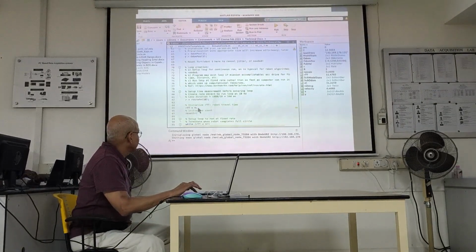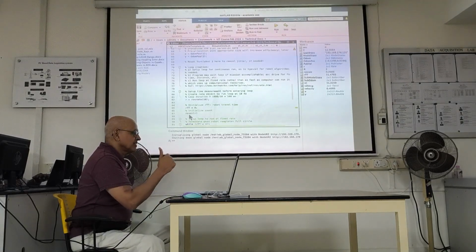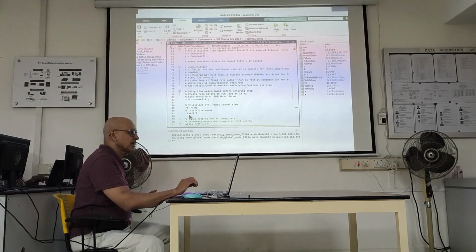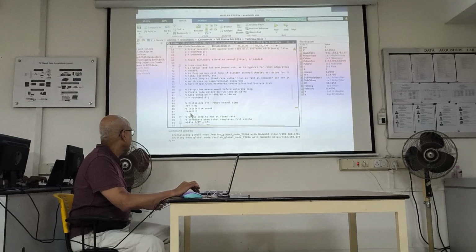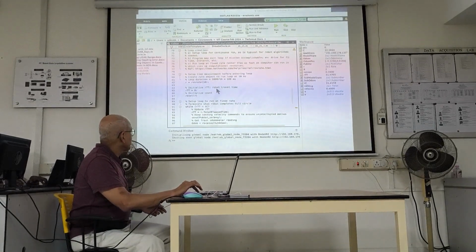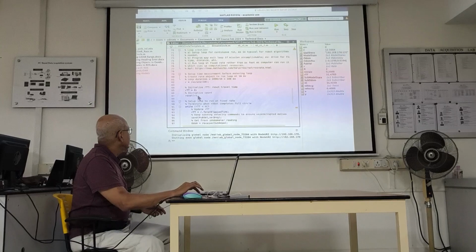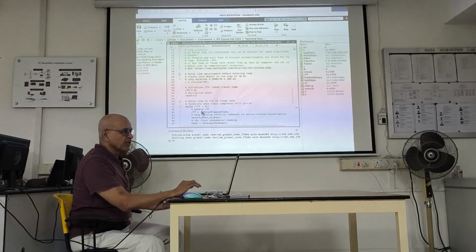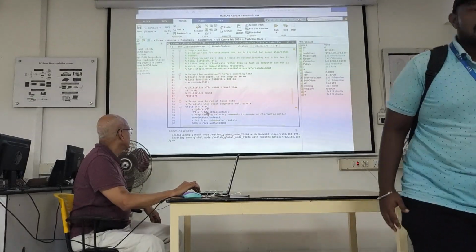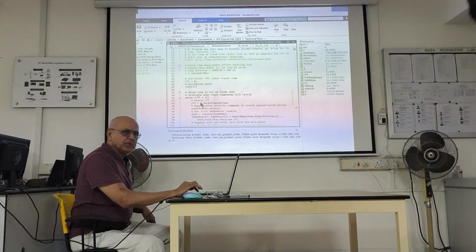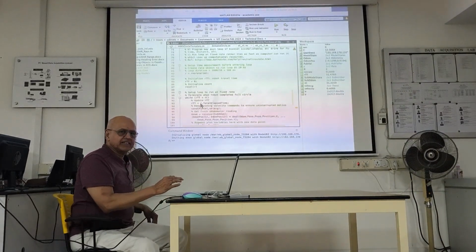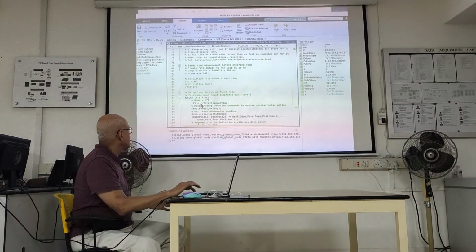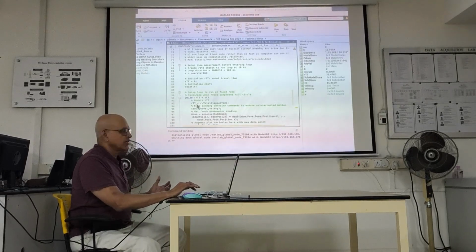So I initialize the robot travel time. I reset the clock, because I have to, right? Because when you're timing something, you have to start with a reset. It's like timing a runner in a race. And then I'm checking whether the robot travel time has exceeded the time to go around the circle. Now initially, obviously, it won't have because you initialized it at 0. And then the first thing you do in the loop is you update it. If you don't update this, it'll run forever. Got it? Obviously, the loop will never be completed unless you keep pushing RTT to the new value.